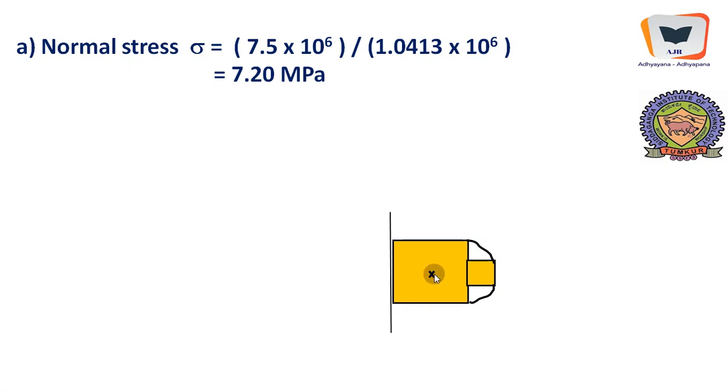So therefore we need to find out the location. Of course this cross section is symmetrical with respect to x, therefore we need to find out x bar. Y bar need not be found because it is 45 millimeters. And in order to find this, we will recall our memory in strength of materials, in engineering mechanics, wherein we knew how we can calculate the centroid of a section. It is the moment of the entire area with respect to an axis divided by the area.